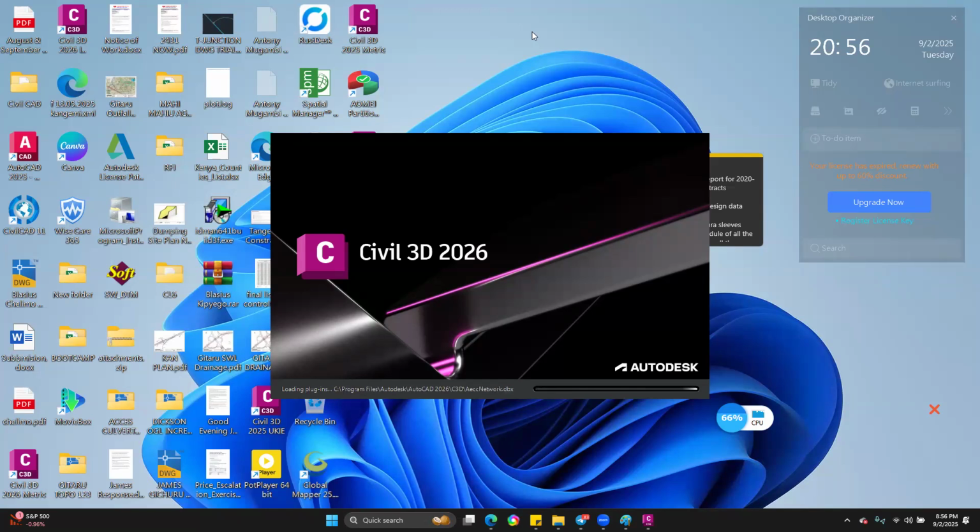I can see we are having a question in the chat box. Assuming we have a divided median road, does the super elevation graph still remain the same? Yeah, basically it will remain the same. You will choose where you want your pivot to be. Is it the median or is it the edge of the pavement? But then again, when you're having a divided median, the curves will still be moving in the same direction, right? So I think those graphs should be the same as well. And I can see, yeah, that's the same pictorial. That's okay.